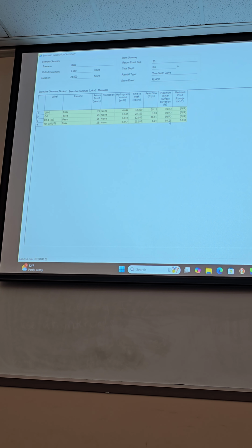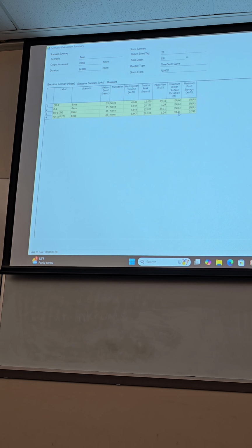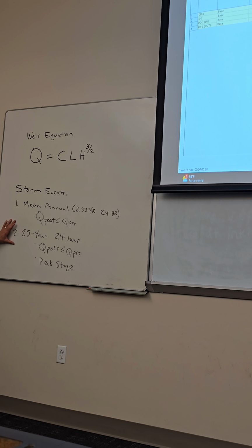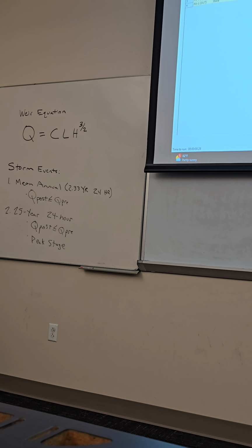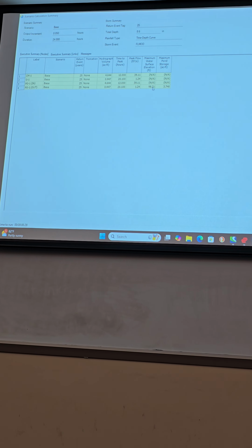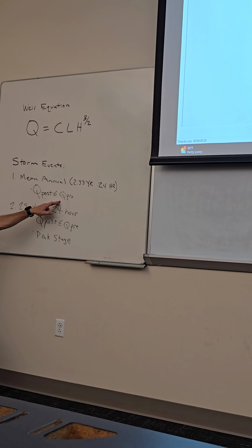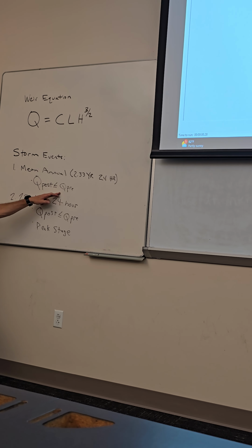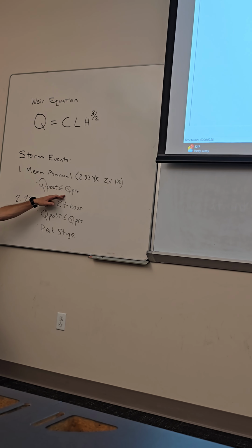In terms of outflow, you're trying to meet this criteria, so there isn't really a set answer for you. But from a design standpoint, you want to make your post-development flow as close to the pre-development flow as you can. Why is that? Cost, right?